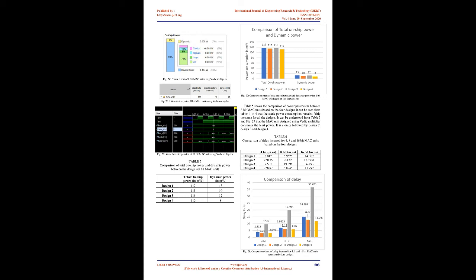It is seen that MAC units designed using Vedic and Wallace tree multipliers have smaller delays and thus operate at higher speeds. The MAC unit designed using the Vedic multiplier consumes the least dynamic power of all the other designs, however it requires the largest number of lookup tables. Furthermore, it can be seen that it requires the least number of nets and leaf cells. Thus, the Vedic multiplier designed using the Urdhva Sutra is a better choice among Booth, Wallace tree, and array multipliers.